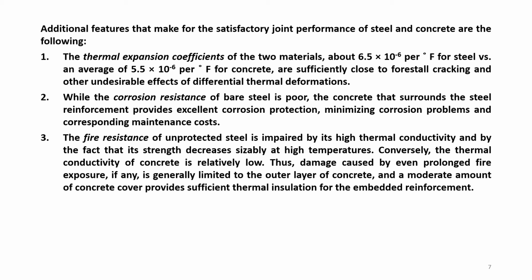The fire resistance of concrete is much more than the fire resistance of steel. As the steel will be covered with concrete, the steel will not expand so much as is expected if it was exposed without any coverage.